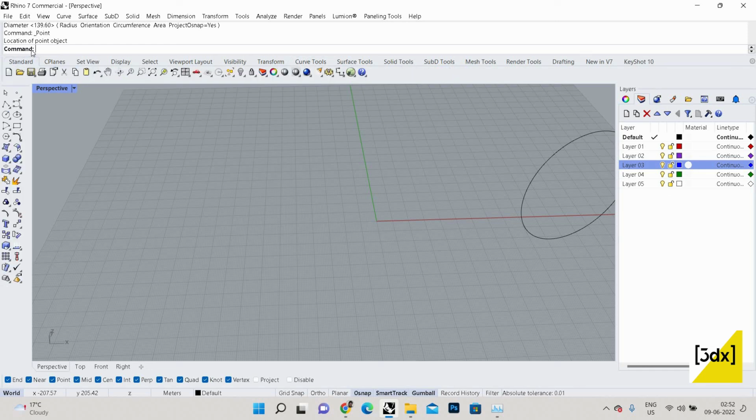You can also draw a rectangle using lines or polylines. But in Rhino, there are some precise things where you don't need to spend a lot of time. You can do it using that. So in that way, rectangle is one of them. So let's go into the rectangle. I just type rectangle in the command prompt. It's asking for the first corner of the rectangle and then the other corner of the rectangle, or the length. So this is a basic rectangle.